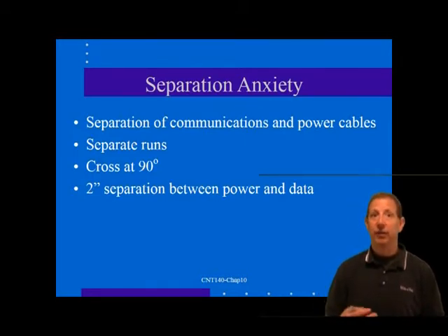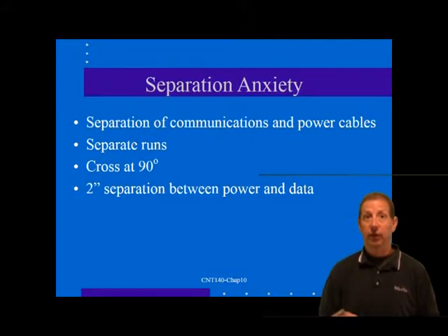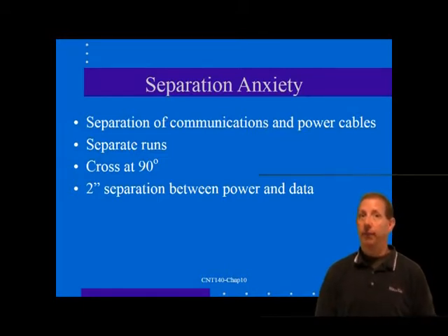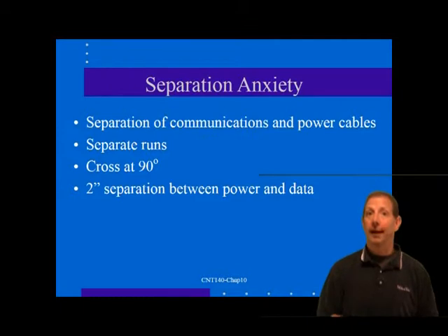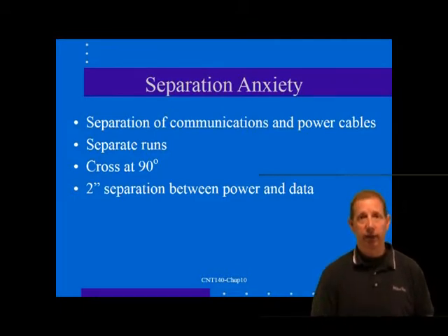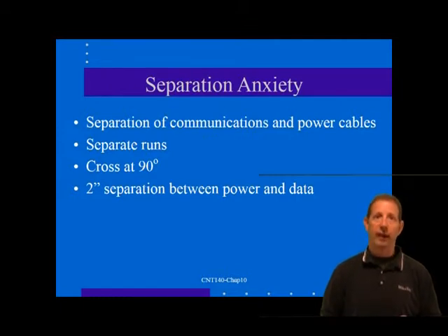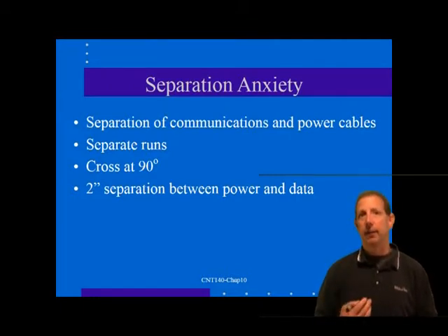It is very easy to run the two types of cables beside each other for hundreds of feet. This increases the chance for interference to couple between the cables, even if the separation is moderate. A good rule of thumb is to place power and communication cables in separate runs to avoid long parallel runs. The cables can generally cross at right angles or briefly run together with little or no coupling. Fortunately, the tight twisting and controlled geometry of modern LAN wiring minimizes the coupling to and from outside conductors.